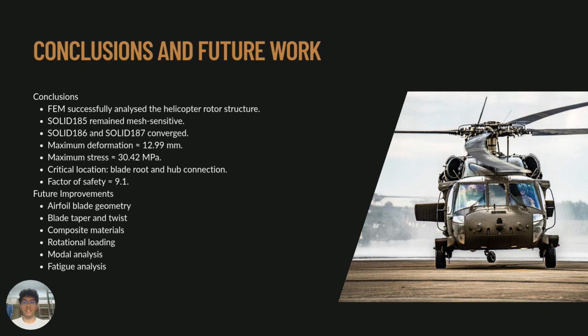In conclusion, finite element analysis was successfully applied to evaluate the structural behavior of a simplified helicopter rotor system. The displacement convergence study showed that SOLID185 did not fully converge, while SOLID186 and SOLID187 achieved converged solutions.